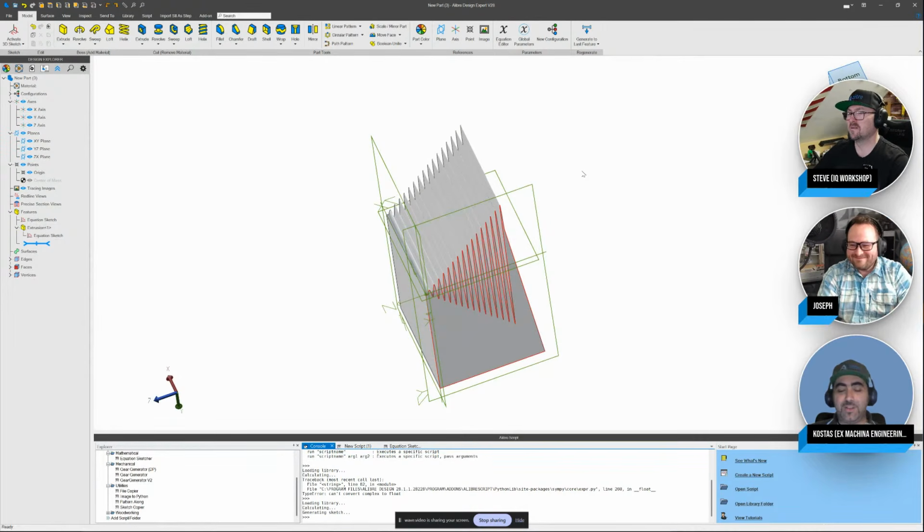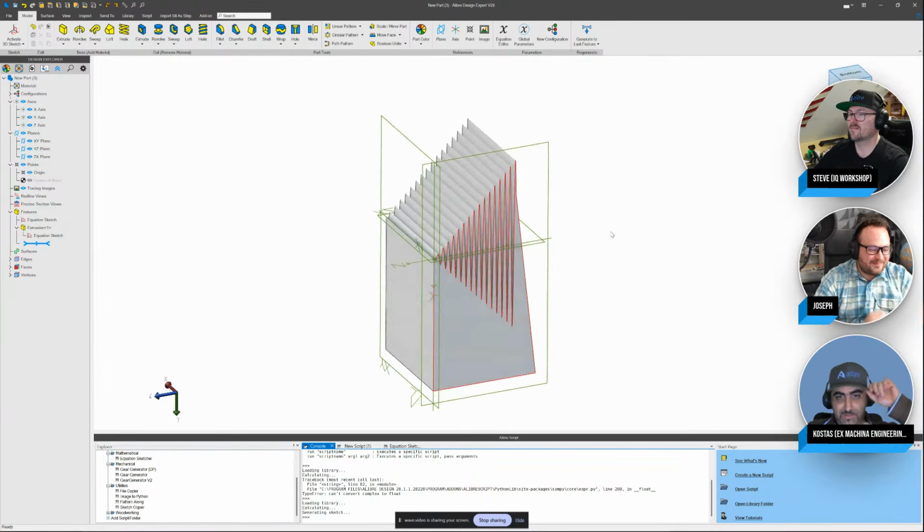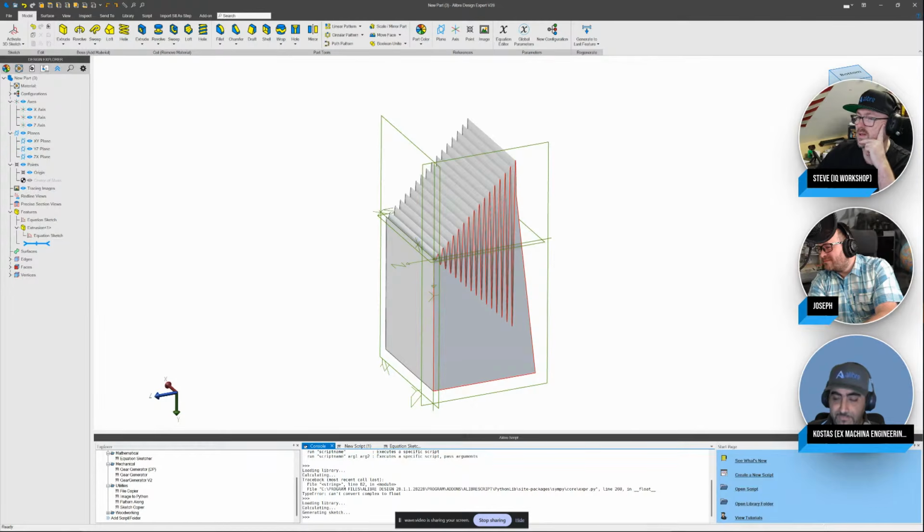So you can do pretty weird stuff, and you can definitely get the third dimension in there going, or control the x direction with one function and the y direction with a second function, which is exactly what you need to draw the involute curve, right, for a spur gear. So you can get that one dimension higher, that equation sketcher, with AI pretty easily, and then you can do some really cool stuff with it. Script in Alibre is really underrated.